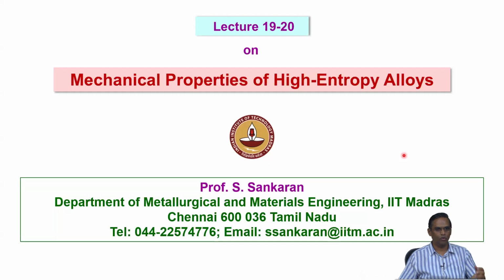Even if you go to any literature, a vast literature is there, if you look at all the as-cast microstructures, you can see already the boundaries are filled with quite a bit of dislocation arrays, and in some cases you can see the hexagonal network in the interface and so on. So this clearly tells us that the dislocations are existing in the as-cast condition. That means they can be manipulated. The stacking fault energy generally comes down.